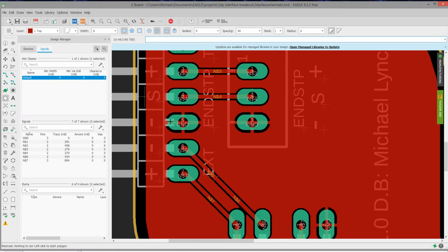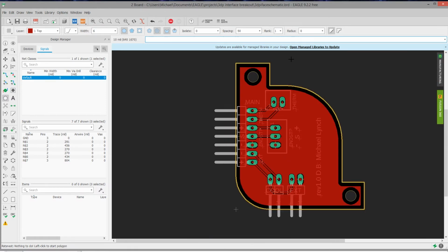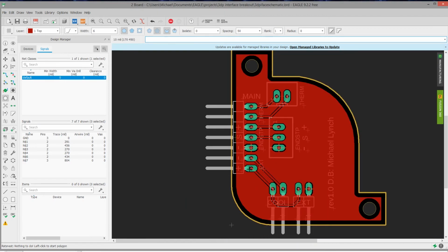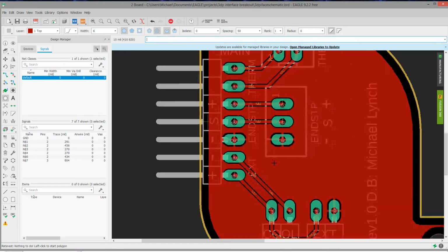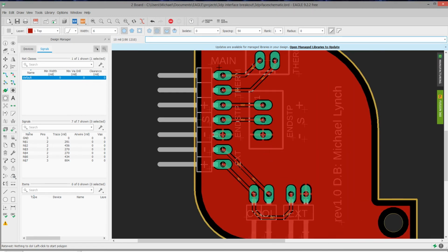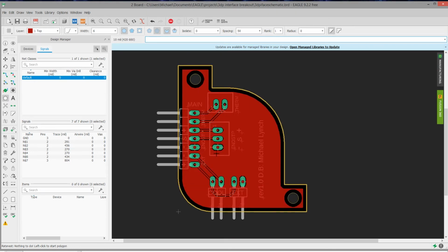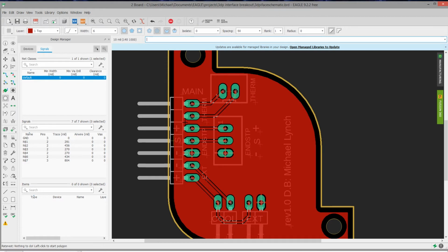As you notice, there are little lines going on each side, top, bottom, left, and right, on each of these ground contacts that splice them into this general ground plane. So it just makes routing a little bit easier. For instance, it can just go all around the board and make a nice clean contact. You don't have to worry about drop off or anything like that. Plus it looks really cool when you have the solder mask on, because this will all be copper underneath. It's usually a good idea to have this underneath the solder mask, which is the mask that protects most of this red area. Of course, the green area is where it's exposed for the contacts. So it just looks really cool to have this whole ground plane here.